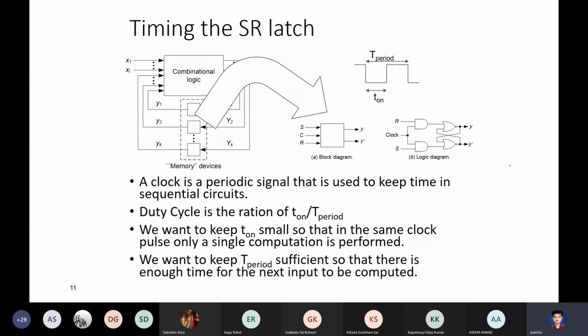So all you see, what is the clock speed of a CPU and all this, is controlled by this factor. Of course, there are other considerations like power, which are the main contributions for modern chips. But the higher you take a clock frequency, you see there's a constraint that T on should be less than T period, and you have a lower limit on T on.